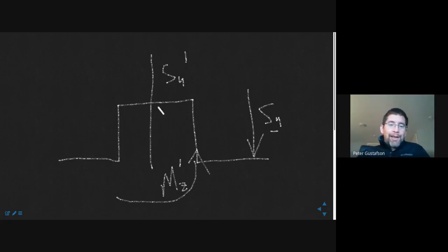So you're going to get anti-symmetry in one portion of the calculation, but then you're also going to have to add to it the shear flows from the torsion, and the shear flows from the torsion would then break the anti-symmetry.